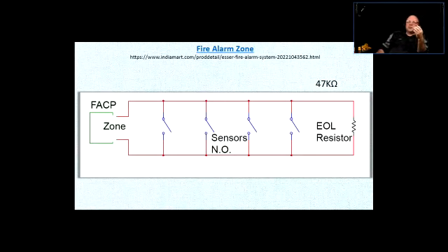And another zone could have a wire going along certain air ducts, right? So if there's a fire in the furnace room, the smoke would go in the air ducts. So there are smoke detectors distributed inside the air ducts, sensing the presence of smoke, and all those smoke detectors along a certain air duct can be connected to one zone. So the zones can be organized in certain ways, and you can combine pull stations with smoke detectors in one area if it's a smaller building and things like that, right?